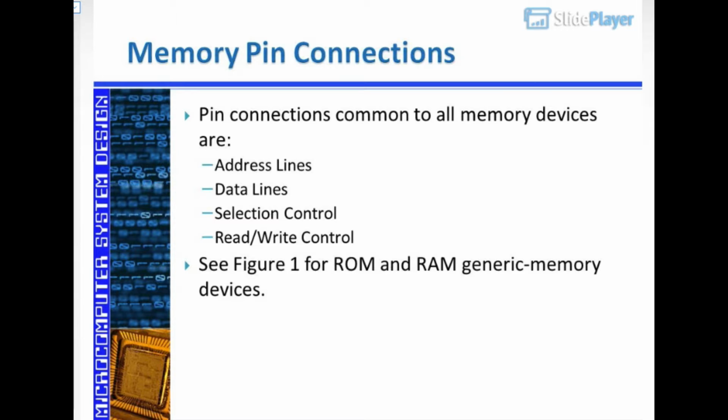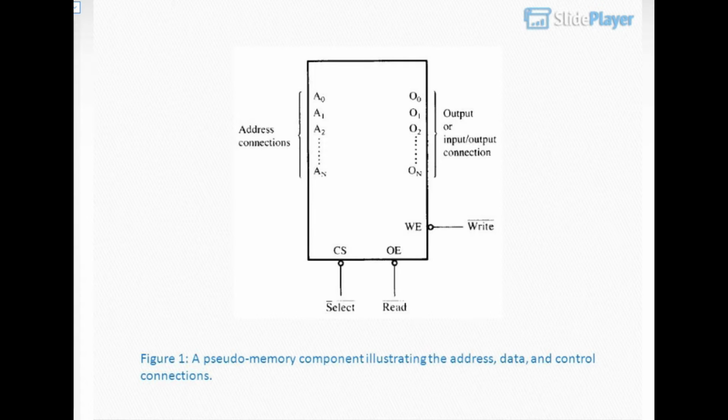Memory pin connections. Pin connections common to all memory devices are address lines, data lines, selection control, and read/write control. See Figure 1 for ROM and RAM generic memory devices. Figure 1 is a pseudo-memory component illustrating the address, data, and control connections.